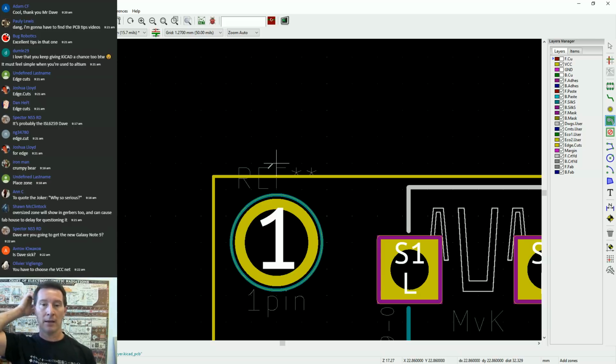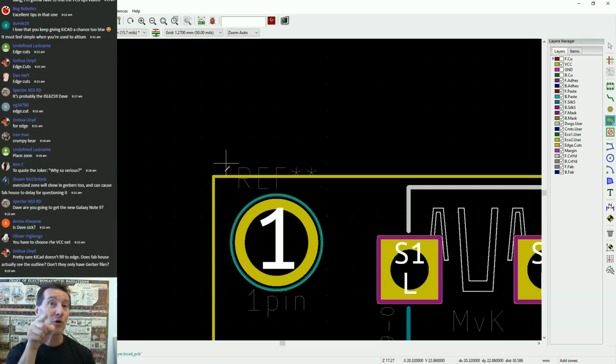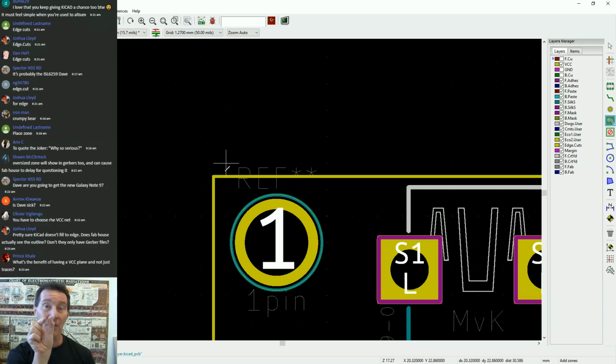But anyway, if you draw them all the way to the edge, like I can't, my snap doesn't go in there. It doesn't snap to object. Anyway, if you take your copper plane all the way to the edge of the board where the board gets routed or sawed or cut off, then if you've got the copper in the inner layers, when they slice or route through it, it can cause little burrs in the copper.